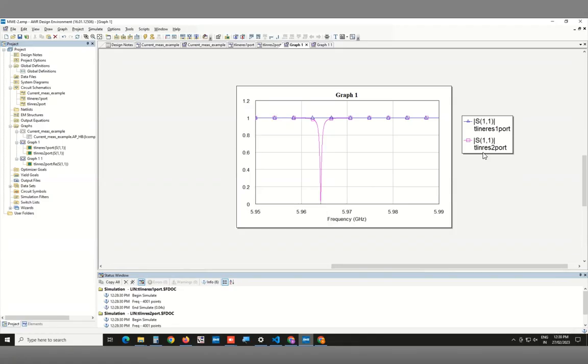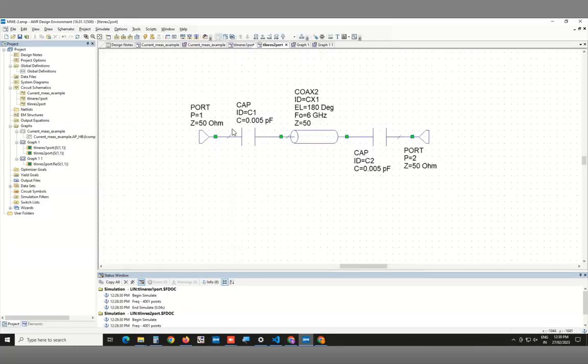Just the pink one is the two-port one, and now we are looking at magnitude of reflection coefficient. And the reflection coefficient is going to 0 exactly at the same point we saw the real part reaching 0 from 1, right? Which is the same as the resonant frequency. Why is this happening? This is happening because now that power is actually coming out of this guy.